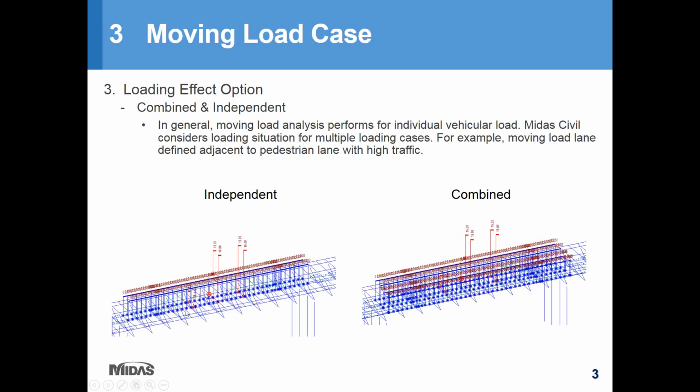I'll demonstrate the load case after all the slides, but for this specific project file, I've defined an HL93 truck and a surface load replicating the pedestrian load.